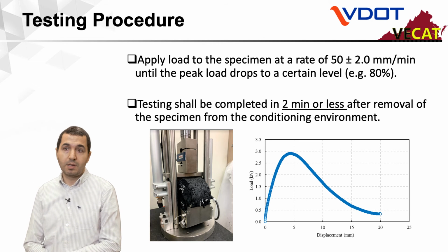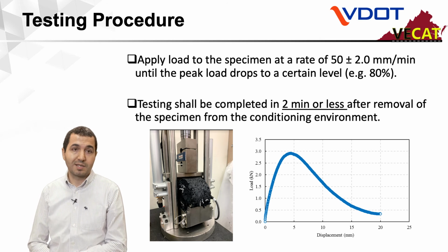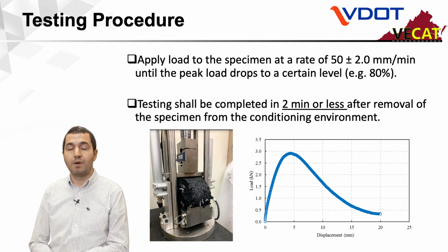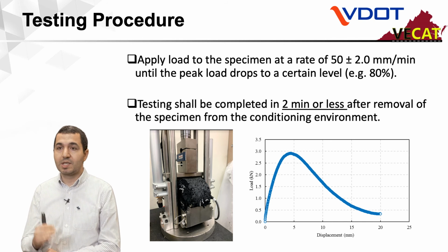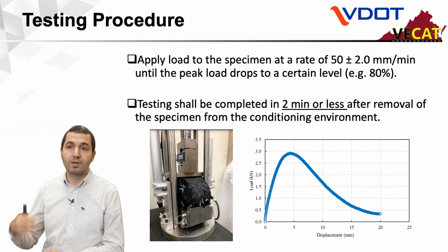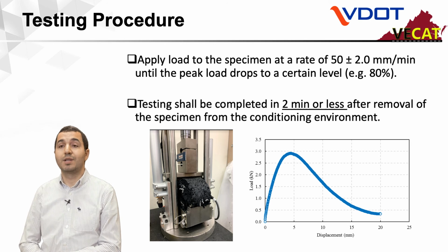And again, this is very important. Testing shall be completed in 2 minutes or less after removal of the test specimens from the conditioning environment. If you keep the specimens longer than that, you will get false positive results on your rutting test here.